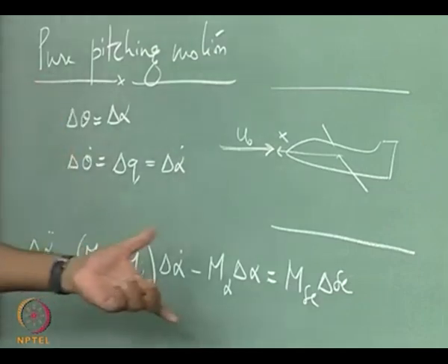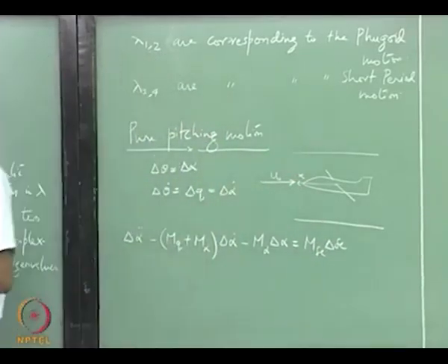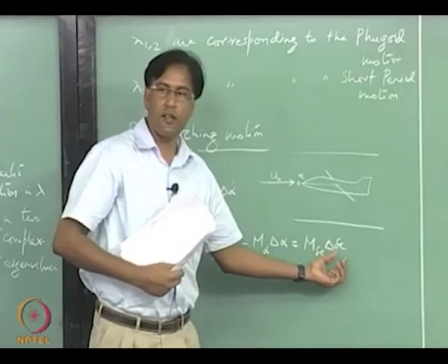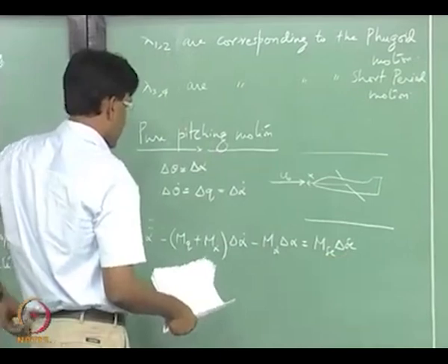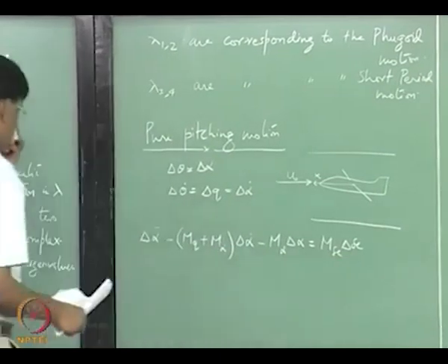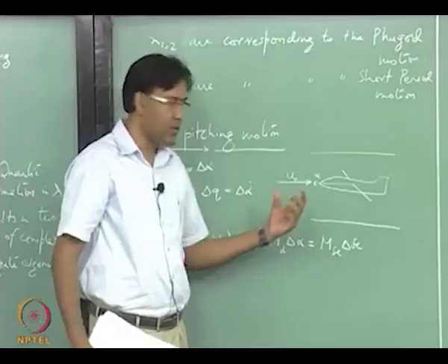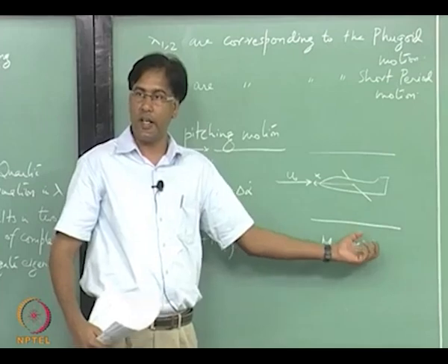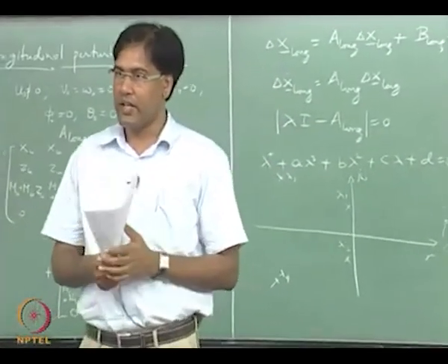Now we are looking at the motion with respect to disturbance coming from the disturbance in the wind, not because we are giving an input to create a disturbance, right. So, we will look at the response in alpha with respect to the disturbance which is coming from the wind and not because of the control input, right. Delta E is the perturbation in elevator, right.